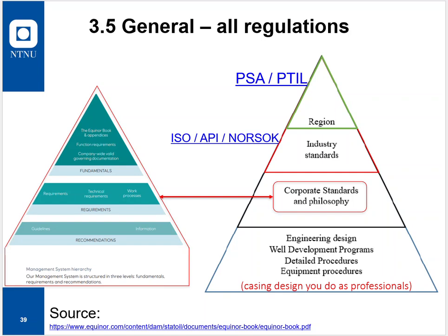Like said, when it comes to the wall thickness, it was initiated by the casing manufacturing industry. They were saying that it's hard to do a wall thickness more accurate than 85% or something like this, 87.5%. So that's why the standard at some point in time said, okay, let's add 12.5% wall thickness reduction. Then we're covering everything.